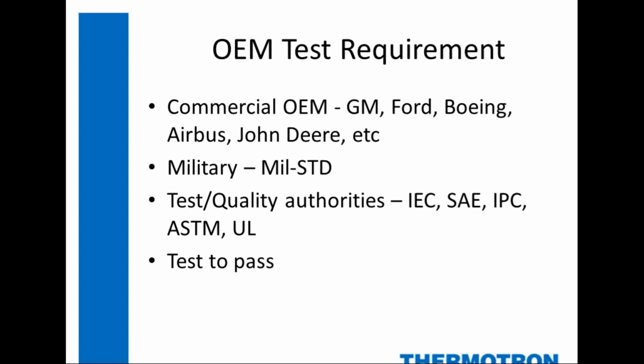So in order to get the confidence for that, they had some really harsh, pretty tough tests that would involve thousands of thermal cycles, thousands of hours of high temperature and high humidity, and then some obscure things like hail gun testing, all to help ensure that those products would last that long. And generally, in contrast to the HALT testing I just talked about, the hope when you're a manufacturer is that you can pass these tests that you're required to. So it's a test-to-pass mentality.